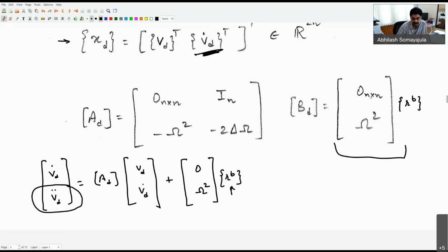Is that making sense? Actually, I'm causing that to be the acceleration. In fact, I was probably even wrong when I said it was directly affecting the velocity. It's actually affecting the acceleration, which cascades into the velocity, which cascades further into the position. Because this is a velocity reference model, the velocity's derivative is taking the direct hit when I apply a step input.